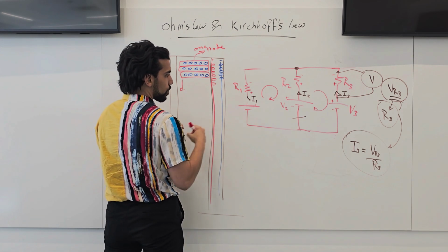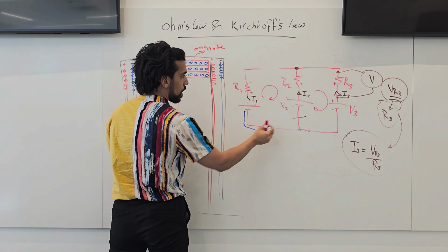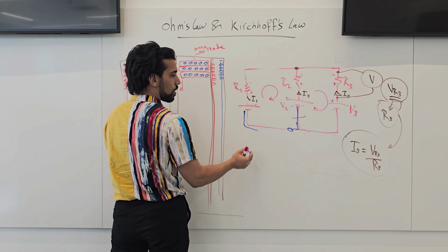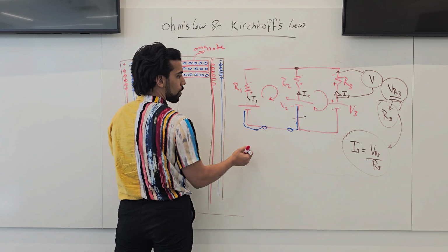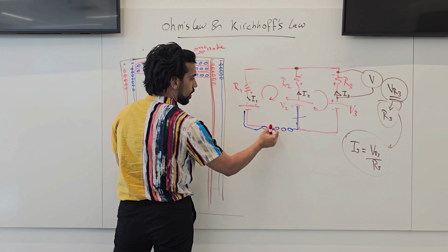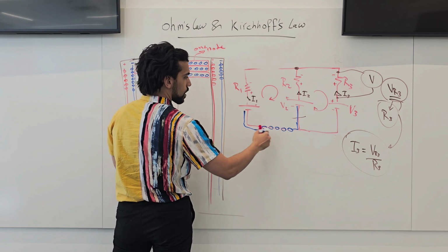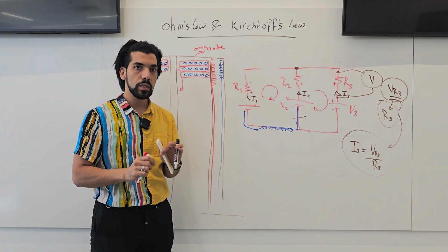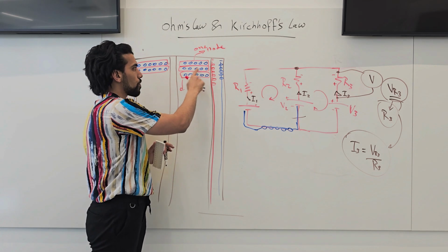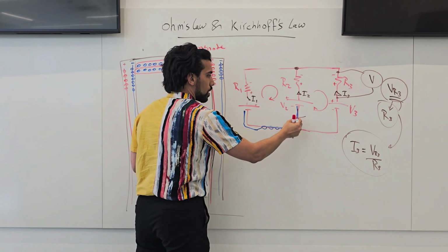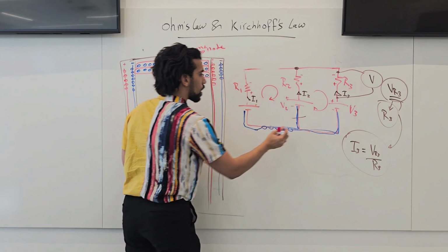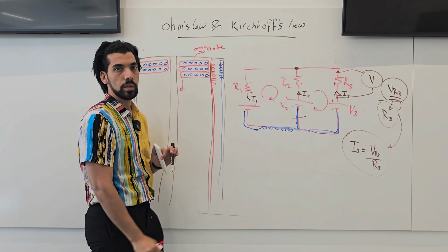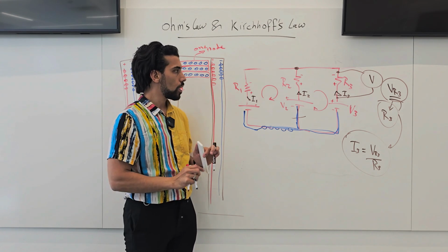So if you have this wire, for example, and this wire that comes from this connection and this connection, this one is going to go in one hole of the 5 holes. So we connect this one, and all of them are connected internally inside the white breadboard. I hope it was clear, and also that each of these 5s is just one node. And it's easy for us to put the pins in each one of them. Okay, hopefully it's clear to you how to do this.